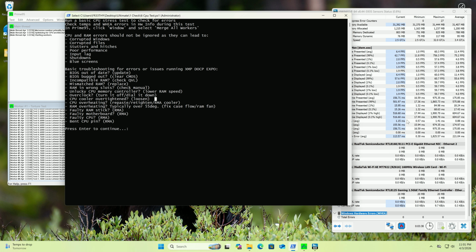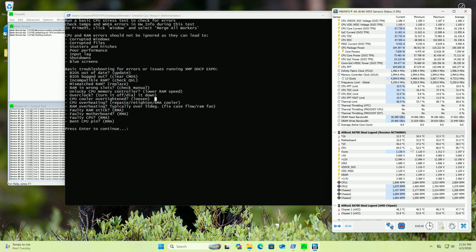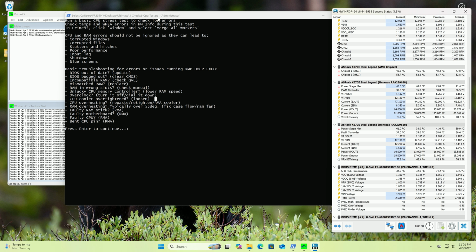Is your CPU overheating? I said, there could be a very thing here. Maybe something wrong with the cooler. Maybe something wrong with your paste job. The cooler isn't in properly. It could be getting so hot to the point where it's going to shut off to protect itself.